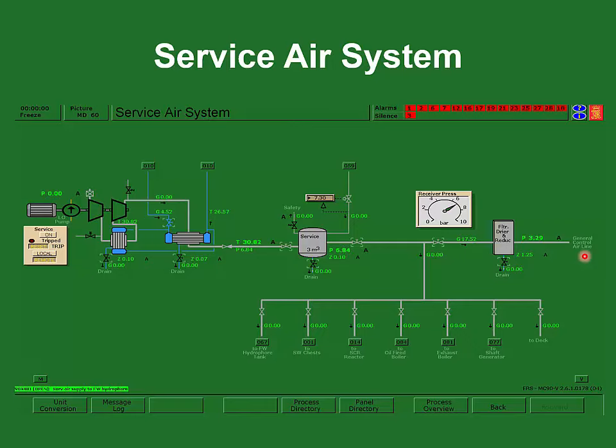In other words, you've got the Coast Guard coming on, and they will test on occasion what is the popping pressure of your safety valves. With local control, you can typically switch it to manual and start the compressor and raise the pressure up in the cylinder until the valve relieves.